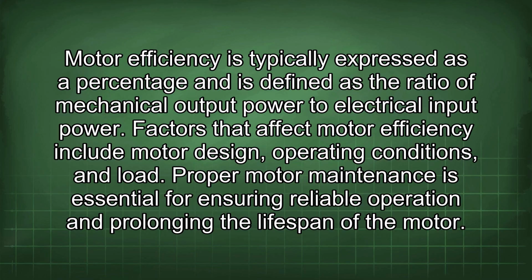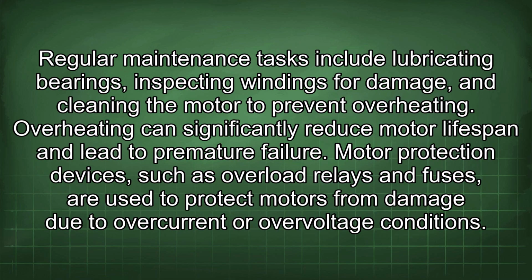Proper motor maintenance is essential for ensuring reliable operation and prolonging the lifespan of the motor. Regular maintenance tasks include lubricating bearings, inspecting windings for damage, and cleaning the motor to prevent overheating. Overheating can significantly reduce motor lifespan and lead to premature failure.